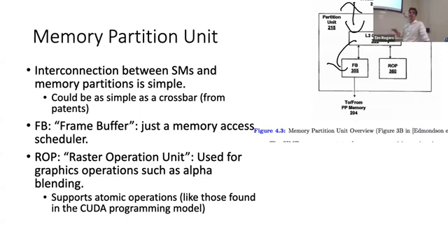How do they do this exactly? Secret sauce. We don't really know what's going on inside the frame buffer to try to optimize things. Is it fully out of order? It's expensive to do fully out of order out here at these memory controllers. Is it partially out of order? Is it just a FIFO? It's actually very hard to even reverse engineer what this is doing.